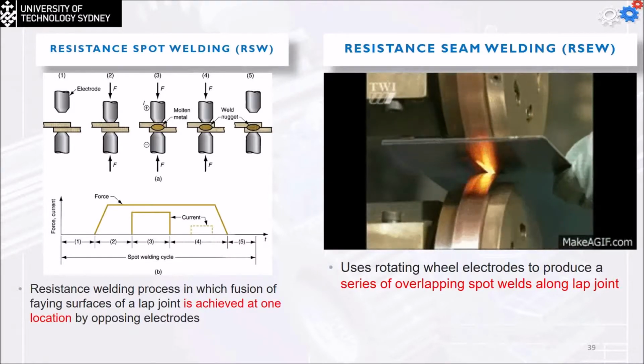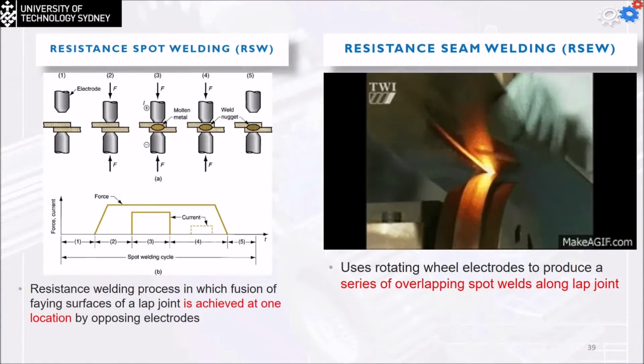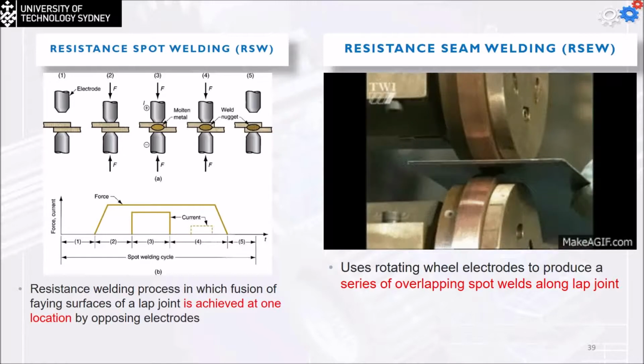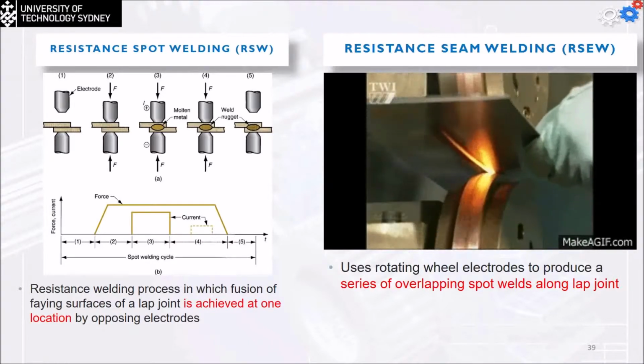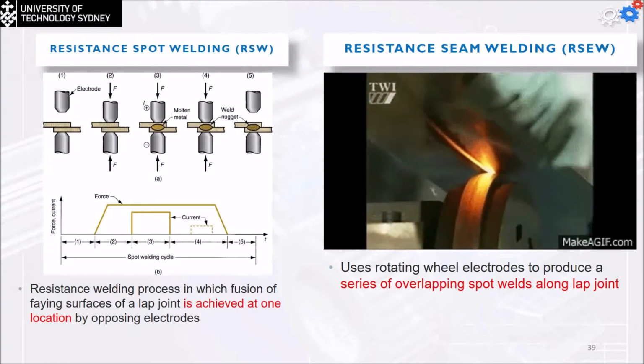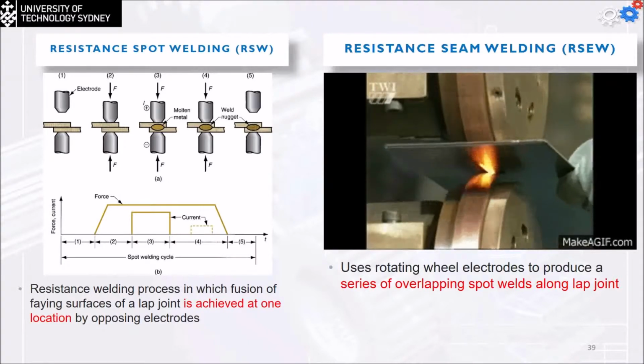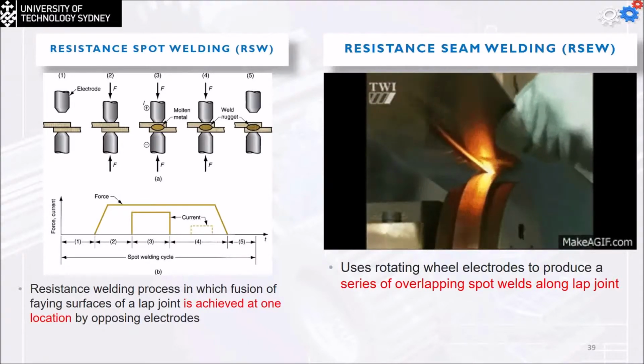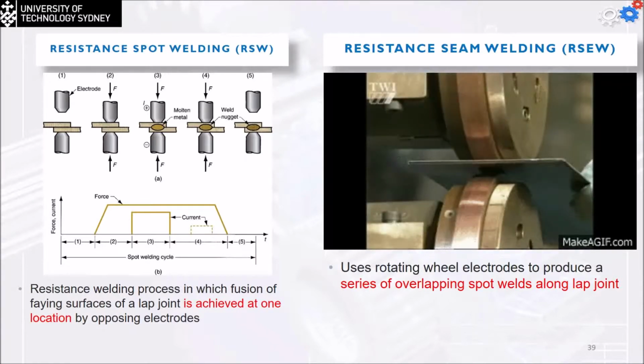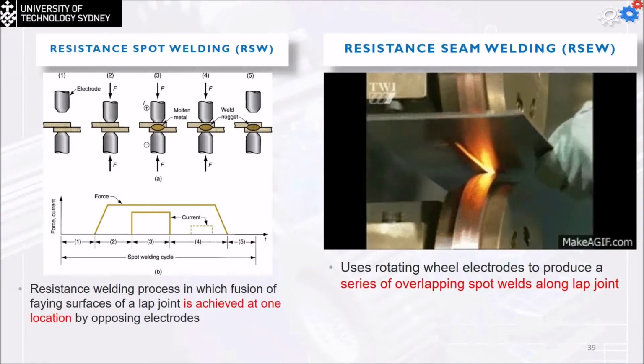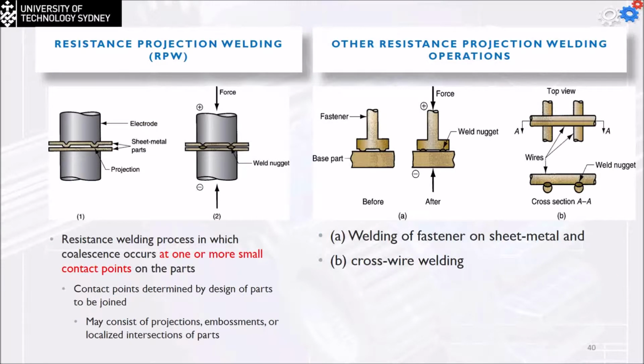So I'm going to apply the pressure, and instead of having the biggest area, the edges are provided as small projections. The current will run between these two parts, which melt and join. And I can also use it in this case, as we do in the case of wire mesh processing.